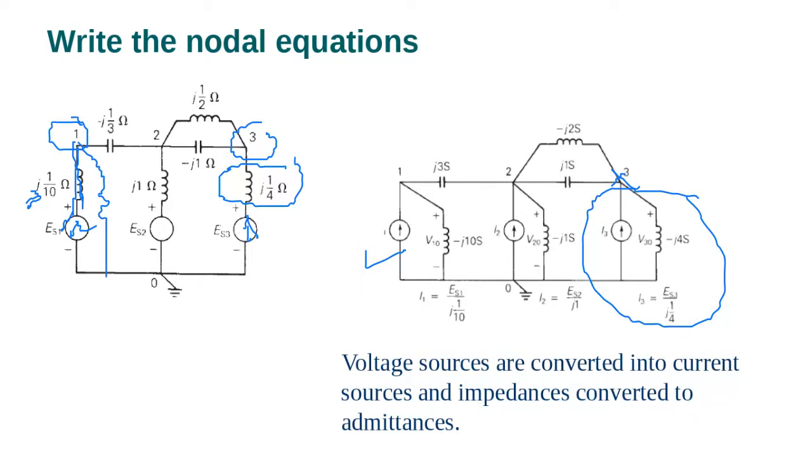We also had students who make mistakes when they do this part in the middle. What you do is fix this bus, this node, and then bring this all down to the earth. You make this part, the voltage, converted into a current source. How do we convert to a current source? V over Z, where Z is in between, which is this one. That is the way you do it.